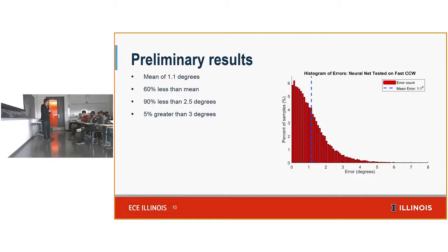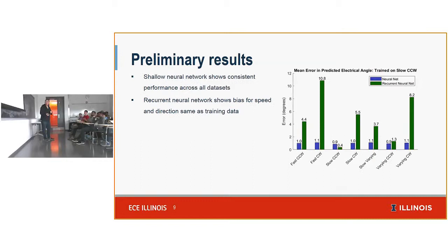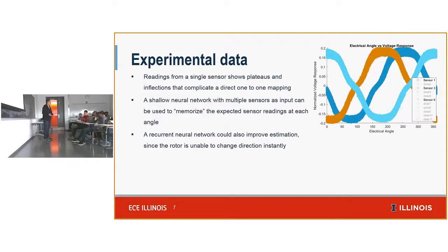For the first experimental data that you showed, the one that said normalized readings, what is that? What kind of B field are you getting over there? Oh, that's B field converted to voltage. So it's linear Hall effect sensors, and zero field has a bias voltage, 1.5 volts, let's say, and positive goes one way, negative goes the other way.